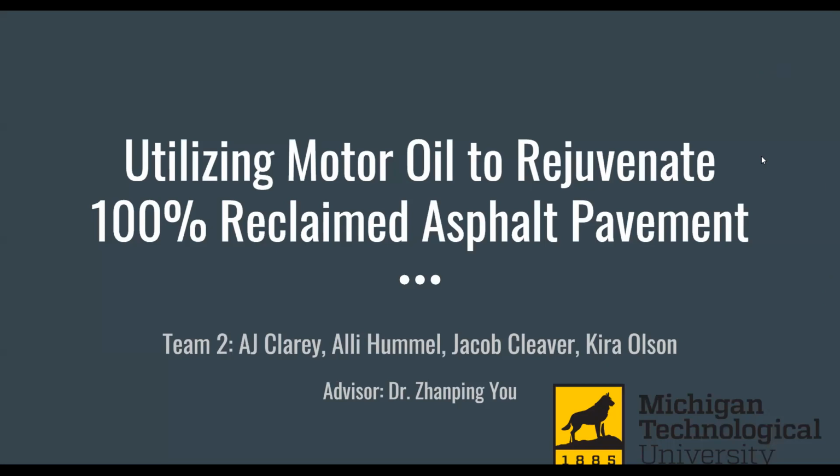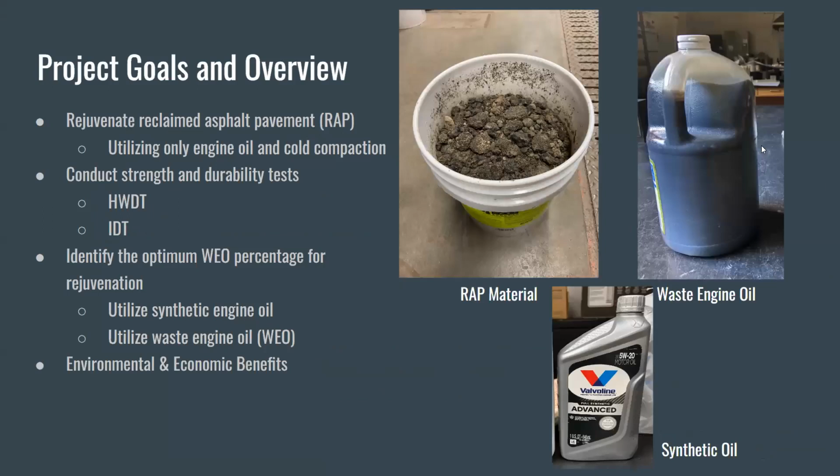Our project assignment this semester was to create a mixed design utilizing two waste products to be a suitable base material in pavement construction. The goal of this project was to determine the optimum waste oil percentage that acts as an adhesive agent and rejuvenates the reclaimed asphalt pavement. The task parameters were that our team could only use the two materials, engine oil and RAP, under cold compaction to create our test specimens.